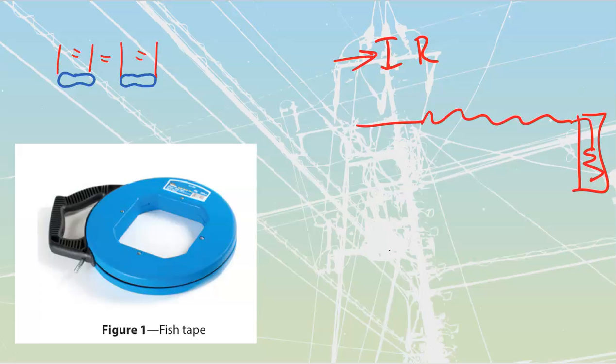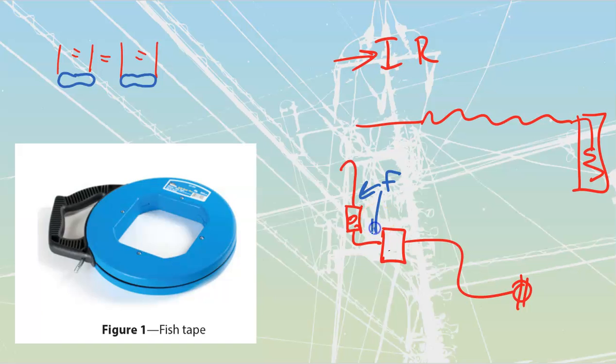It's got to be an either-or type of situation, because if this is where my service entrance comes in, we'll just draw a little meter base over here, and we'll take that to a panel. And then we'll go from that panel, we'll take that thing over to a receptacle. Of these, this is going to be my feeder section, all of this going from here to the panel itself. This is going to be what we refer to as the branch circuit section.